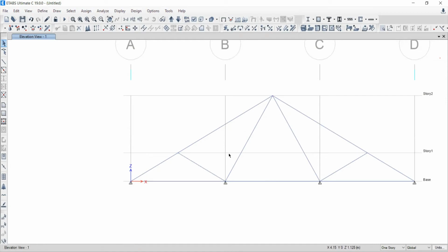But if you are doing the same thing from right to left, what will happen? Can you guess anyone? Maybe the box will touch. Last window selection will be selected. Okay, what will happen if you are dragging from right to left? The things that are going to be cut by this box will be selected, plus the things which are coming completely inside of this box.